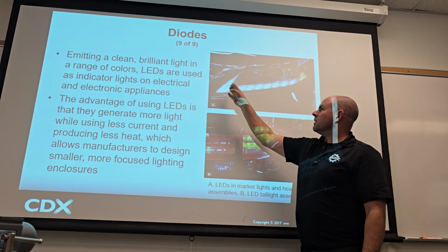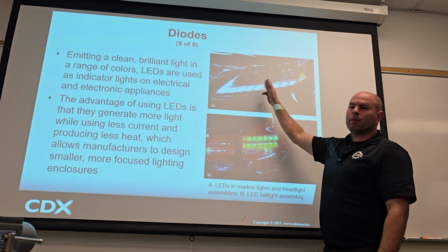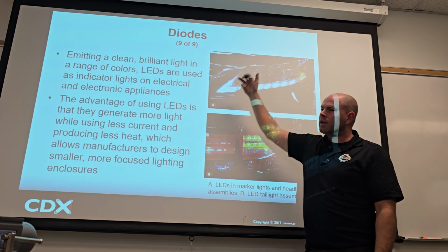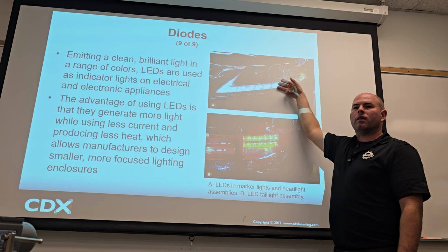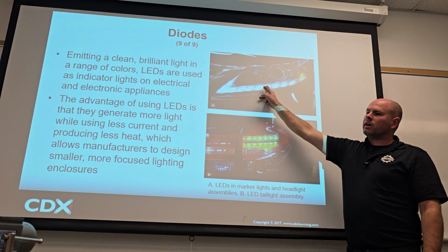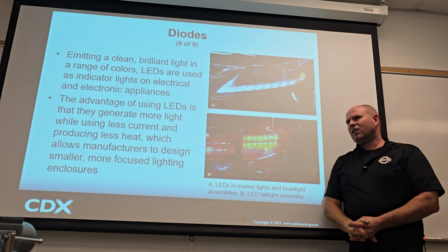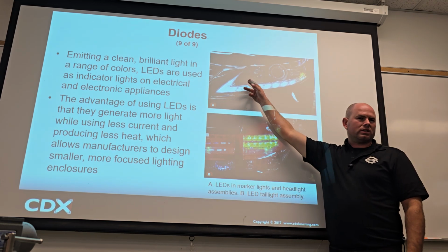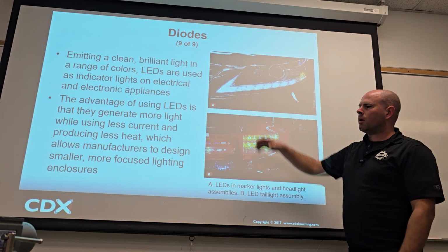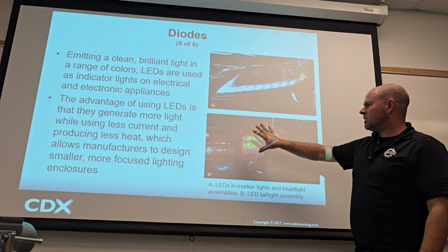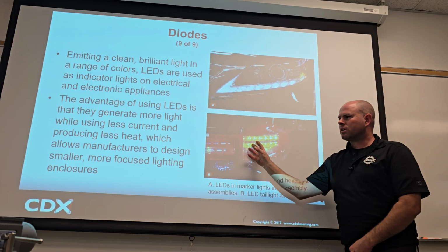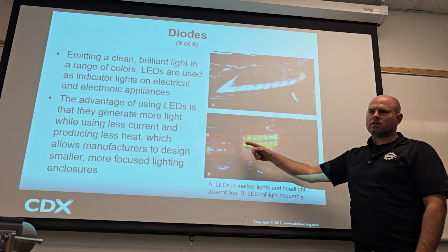There's not a plug here, a plug here, a plug here. There's one, and then it goes through the circuit board. A lot of times when the individual LEDs fail, that's actually a pretty easy diagnosis. Now, they might have failed for a reason. You might have a crack or something and water's getting in there. That'd be pretty common. And same with this. If this doesn't work at all, it's a little harder diagnosis than if some of the LEDs are out.